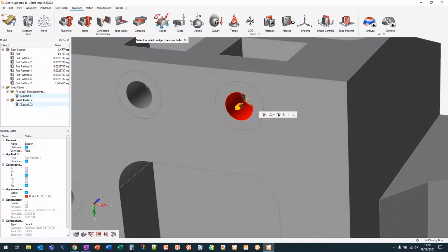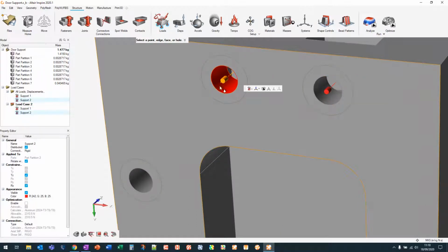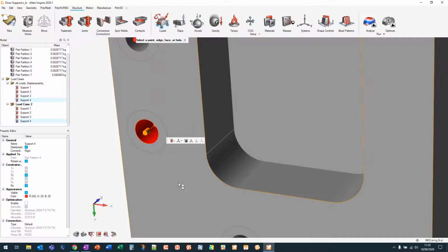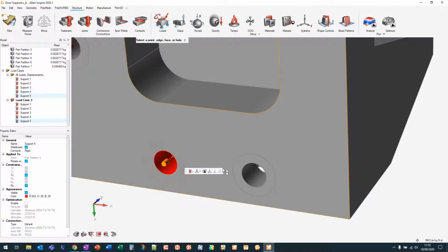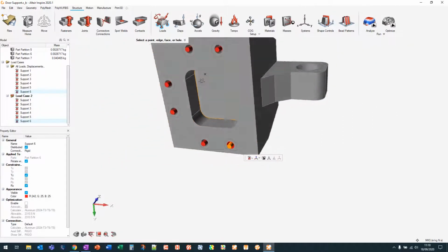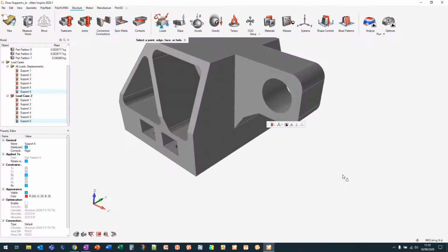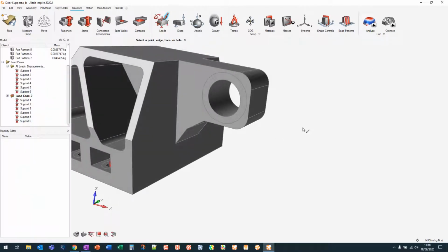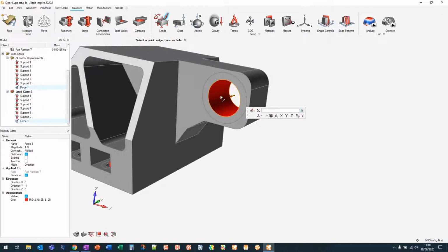You'll also see a load case is now created too. So we'll do this for the bottom 6 supports. Just left click within the cylinder. And those are the supports created. Another thing that we now need to do is apply a force. So we'll change this to force, and let's select the center of this point here. We'll go for a value of positive y.